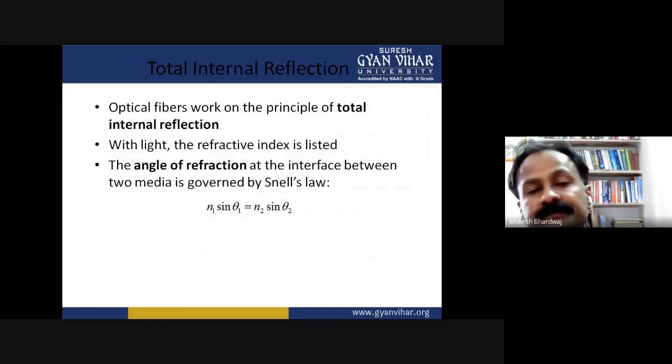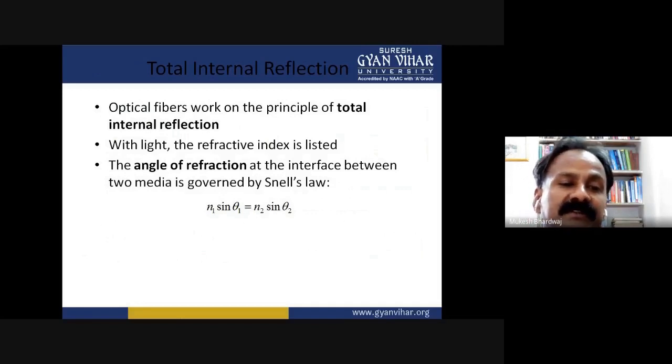Small size and weight. Optical fiber cables are developed with small radii, and they are flexible, compact and lightweight. Fiber cables can be bent or twisted without damage. Further, optical fiber cables are superior to copper cables in terms of storage, handling, installation, and transportation, while maintaining comparable strength and durability. No physical electrical connections are required between the sender and the receiver. And as fibers are very good dielectrics, isolation coating is not required.